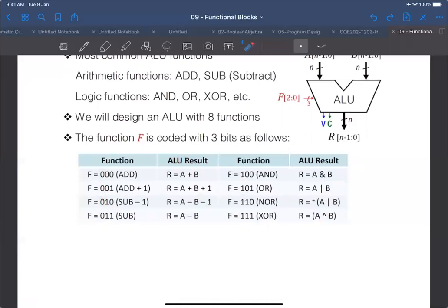So it makes sense that we will have one path of the ALU to calculate the logic results, and another path to calculate the arithmetic results, and then an n-bit multiplexer to choose between the arithmetic and logic paths. What do we use for selection? We use the most significant bit of F, either 0 or 1.